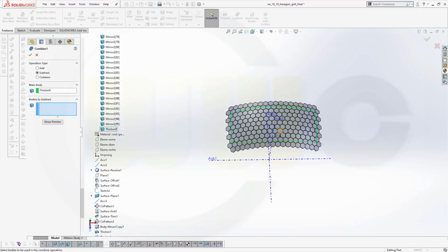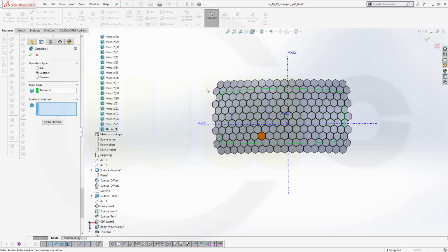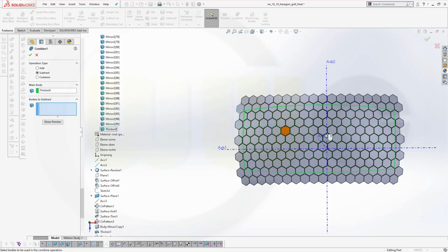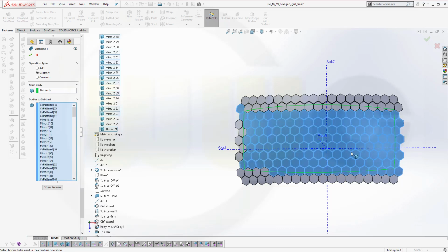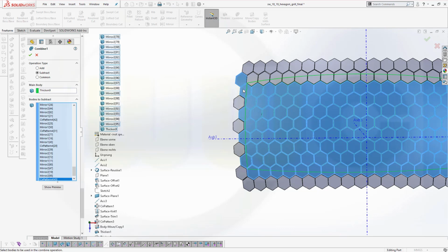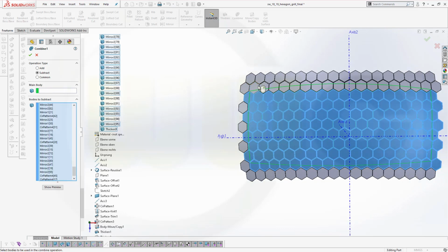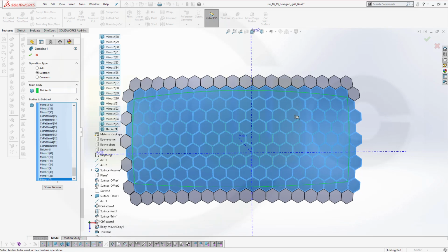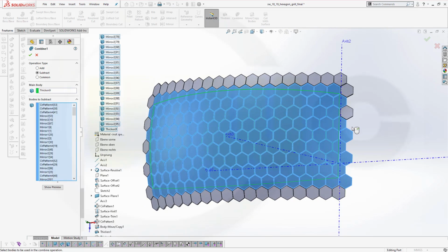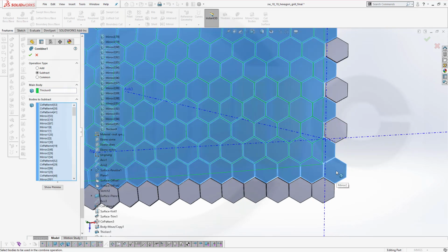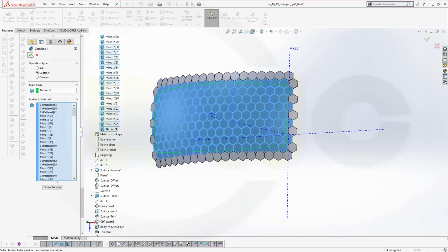So let's try to select them as fast as possible. So let's move this like that, and then make a sort of rectangle selection like this, and see how many we can get. Yeah, but this should be in the selection. This one, that one, this one, no. But those should be in the selection. And it's all because of SolidWorks being a parallel program. I can't make a union of those separated bodies. So that should be outside the range. Yes, this looks okay. So confirm.